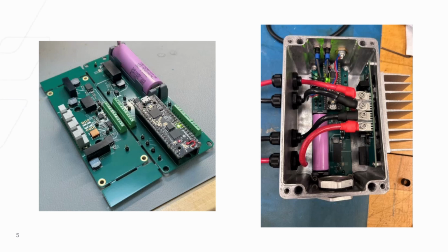On the left, we have our PCB, which includes two boards. The high voltage board handles the conduction, and it senses parameters that help our control board on the right make decisions on when to trip the circuit. It uses a lithium-ion battery and an FPGA, which makes calculations faster than a typical microcontroller. And on the right is all our components in the final enclosure.